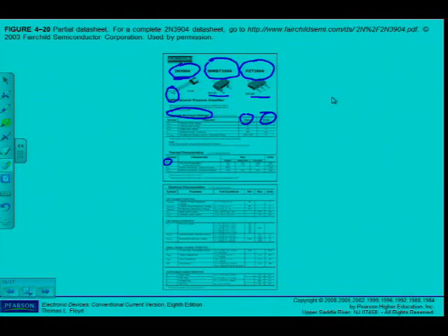You'll just have to follow me there in the book. As I can see there, power dissipation, which is total device dissipation, and then you will see there are the 3 transistor names: the 2N3904, the 2N3904, and the MMBT3904. There's the one, there's the other one, and the PZT3904. And you will see that they have different power dissipations.